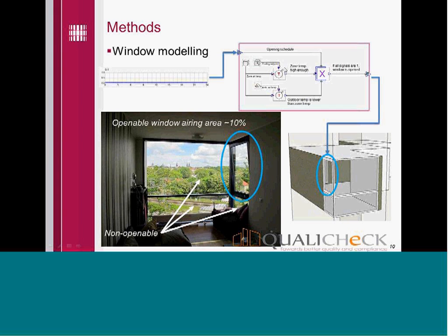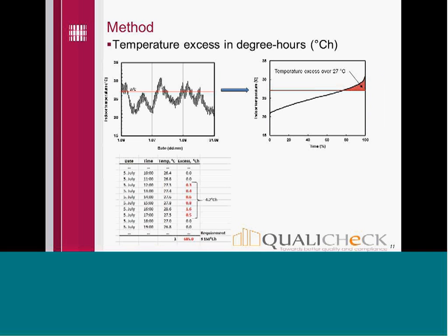So this kind of logic needs to be in the simulation software, and this can limit the selection of the software, because not all tools have such sophisticated modeling features. But basically it is possible to model also without window opening, but then temperatures will be higher, and in some cases the difference can be quite significant.